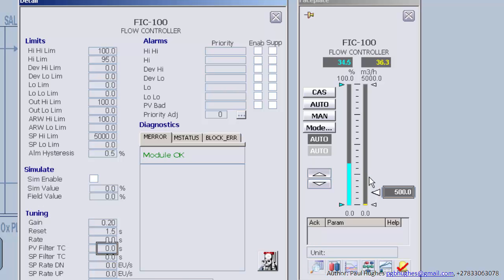And if we fall back to the estimated value, how do we make sure that when the transmitter becomes good again, or moves into a region where it's reliable, the transition between the estimated value and the good field value is smooth, in the upward direction as well as in the downward direction? That's the question we need to answer: can we build an estimation for the flow at this low region to give us a smoother measurement at this turn down point?